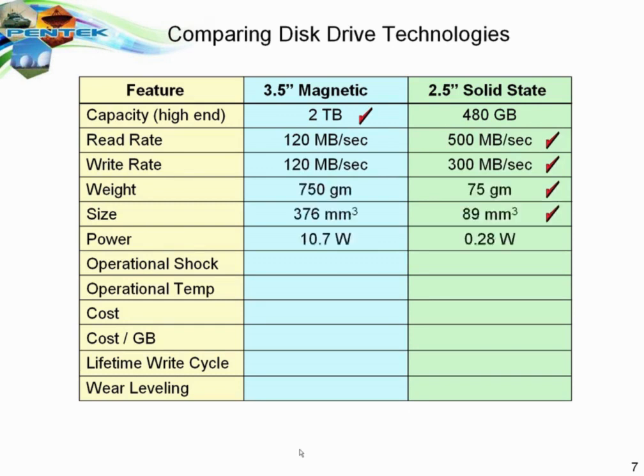We do have a system CPU and operating system that's managing everything, but they do not touch the real-time data. They're simply there to initialize the DMA controllers, the RAID controller, and the I.O. module, and manage the overall performance through interrupts. So it's an interrupt-driven management facility that the CPU does, but the data itself is not touched by the CPU, and that's how we can achieve real-time operation, even using a non-real-time operating system.